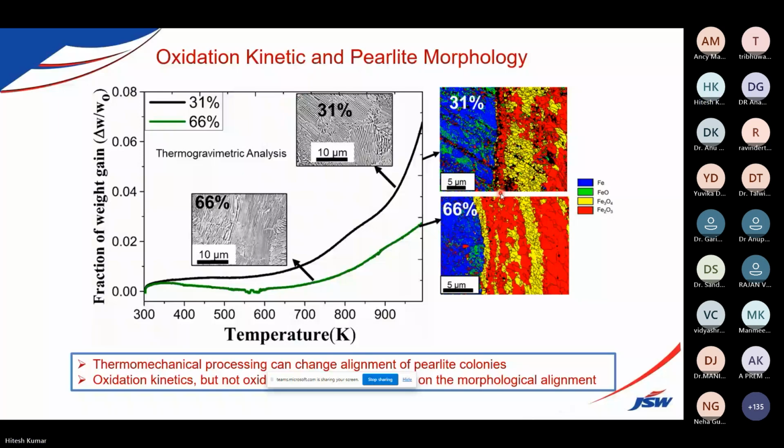If you want to analyze how much coating thickness is generated by your different experiments, the best way is to see the cross section, analyze it at 3, 4 or 5 different places, and then take the average. That will give you an appropriate idea of how much coating thickness can be formed and how you can improve it.